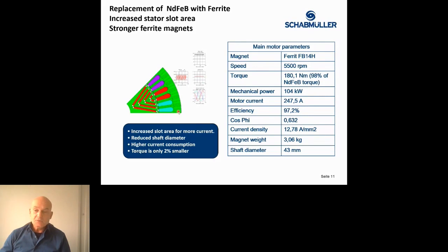Of course, this is a theoretical study, and not all designs will allow finding a way to place enough ferrite material into the rotor. Not all designs will allow reducing the shaft size, and maybe one will also be limited in the increase of slot area to place more copper into the motor. Not to forget the situation with the power factor of the motor.